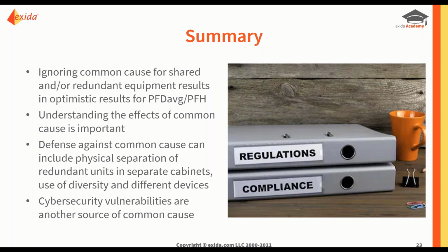You can include physical separation of redundant units, for example, in separate cabinets. You can use diversity, you can use different devices. All of that has to be weighed up against the additional costs, certainly with diversity for the maintenance.